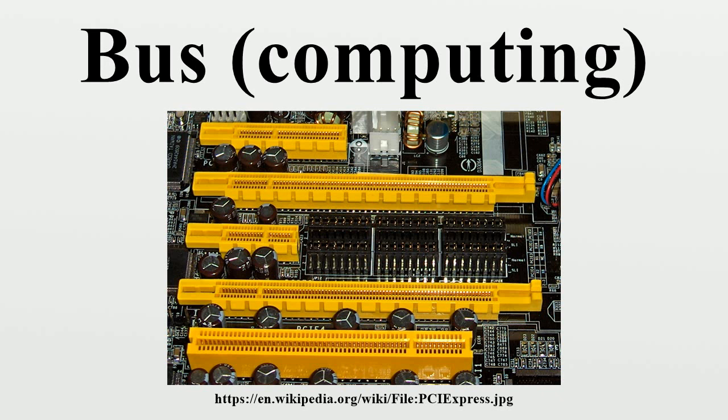To provide modularity, memory and I/O buses can be combined into a unified system bus. Later computer programs began to share memory common to several CPUs. Access to this memory bus had to be prioritized, as well. The simple way to prioritize interrupts or bus access was with a daisy chain. In this case, signals will naturally flow through the bus in physical or logical order, eliminating the need for complex scheduling.